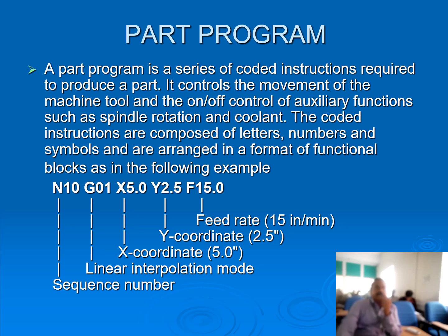Here you can see N10, G01, X 5.0, Y 2.5 and F 15.0. All these letters and numbers have their own explanation. For example, N10 is a sequence number.